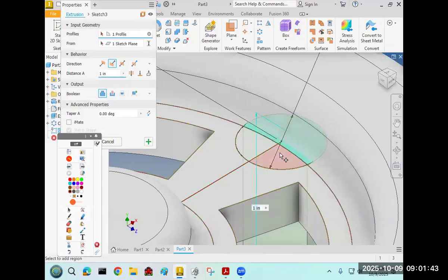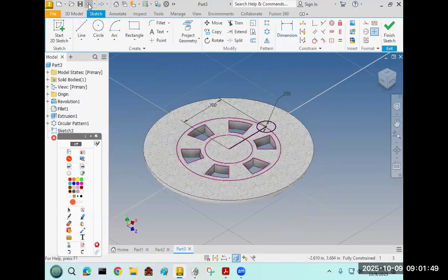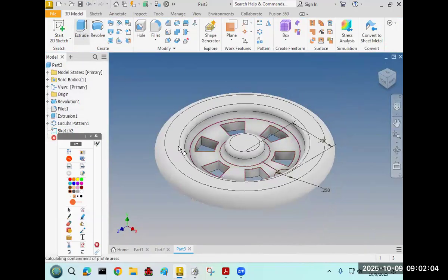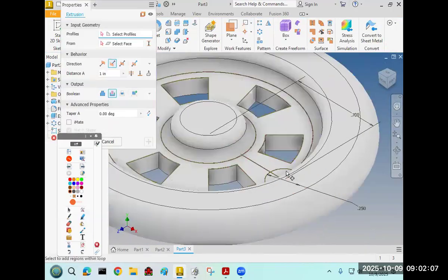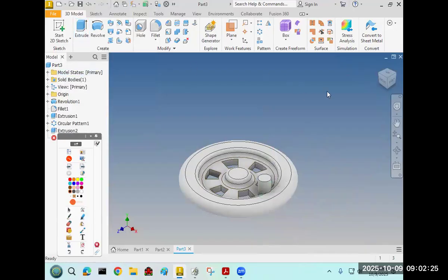You may have to zoom in to get everything. That's weird. Okay. All right. So going back a second. How far are you? Do you have the slice graphics? Okay. We just need a circle that is 0.25 diameter. And we'll finish sketch, extrude, and find somewhere that you get the full circle, usually towards the edge of the circle. You can select just the portion and then go around, select all the portions, but it's easier just to find a spot where it's fully highlighted. And the length we want to extrude is 0.375. Correct.